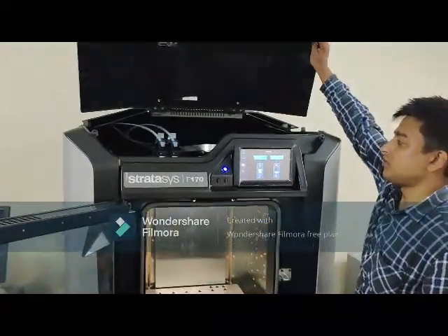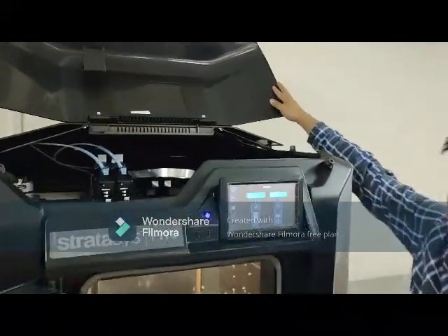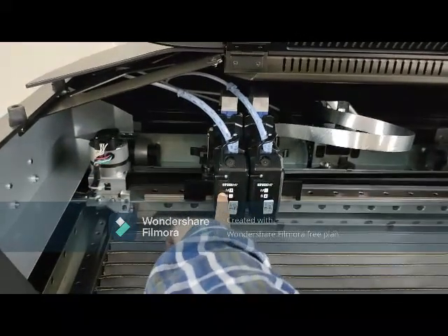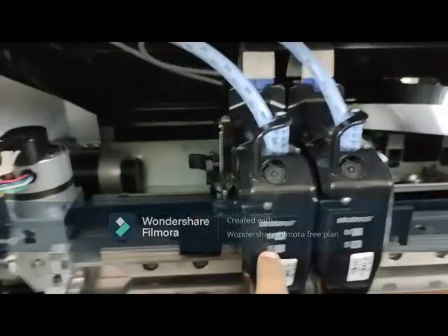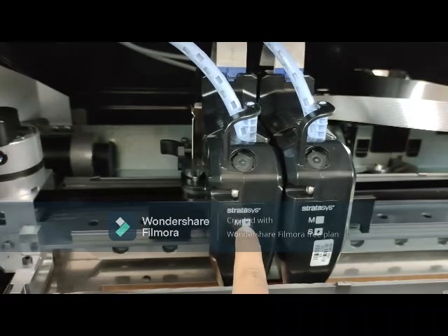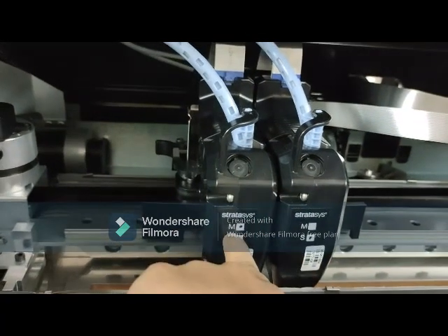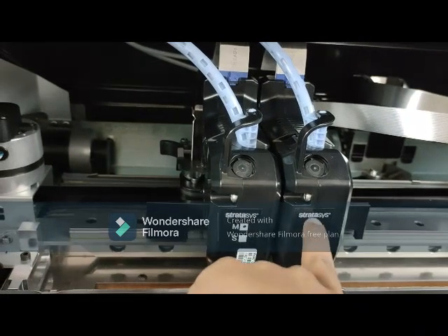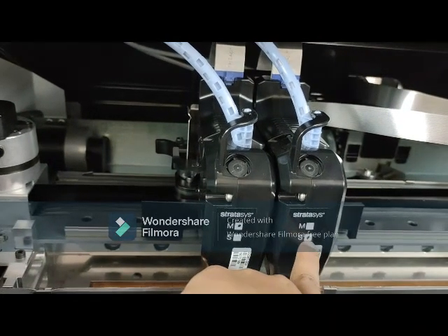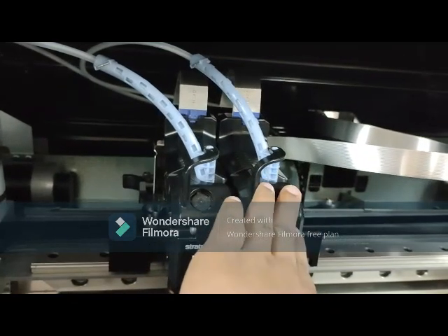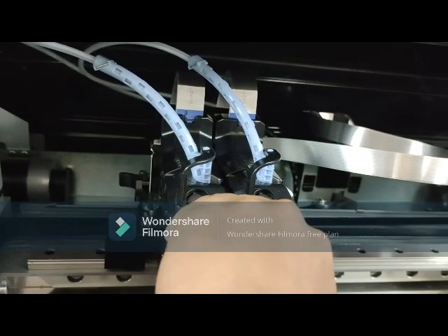Talking about this portion, we have this head here. In the head section you can see we have two different types of thing. So we can move it. Okay, fine, I'll show you. We can see here we have M and S. This M means model material and it is marked here. That is, this head is used only for model. Similarly we have here M and S, and it is marked here S, that is support material. So this head is used for support material and this head is used for model material.